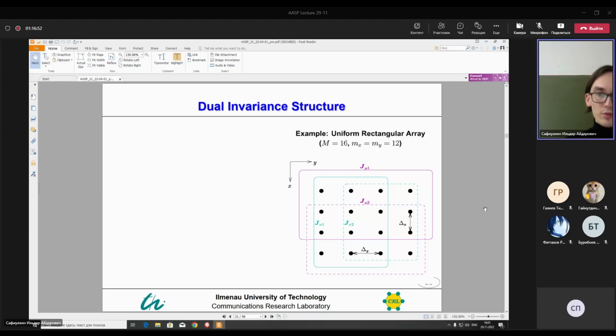And we choose these using maximum overlapping. So, for example, let's look only at this part with only these 3 elements for the x-axis. In maximum overlapping, we will choose first, second, and third for the first selection matrix, and second, third, and fourth for the second selection matrix.